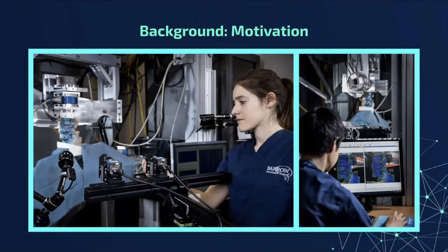Digital image correlation, or DIC, is an optical strain measurement method which is capable of comprehensively measuring strain distributions on non-homogeneous surfaces by tracking deformations in surface speckle patterns. This makes it an ideal tool to use when analyzing tissue, or tissue instrumented with a supporting construct, such as the cadaveric test models used by the Spine Biomechanics Lab, as can be seen in the pictures on this slide.